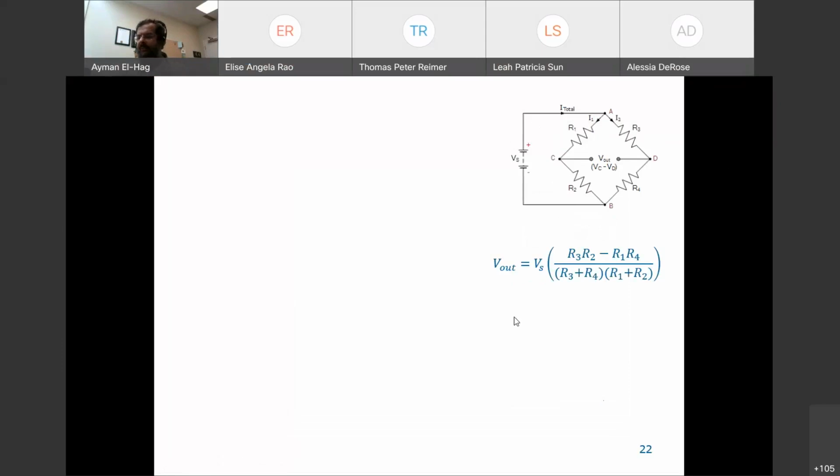So let's review what we have done so far so that we are on the same page, because this is the question of the Wheatstone bridge. It will be a question in the midterm for sure. So basically we have our beam here, connected, could be in any configuration. And then I will have one or more strain gauges. So let's say we have one strain gauge here.